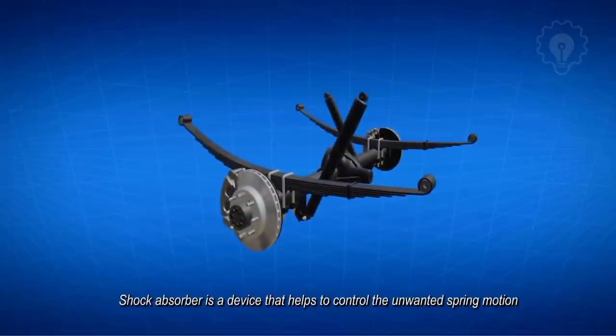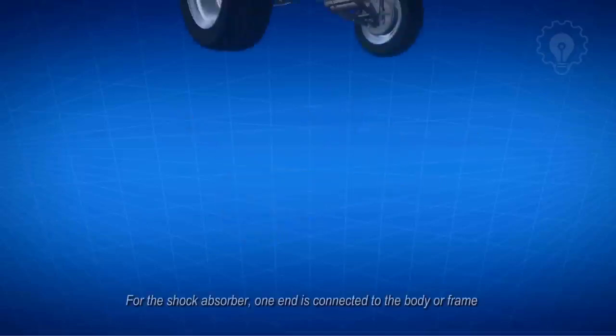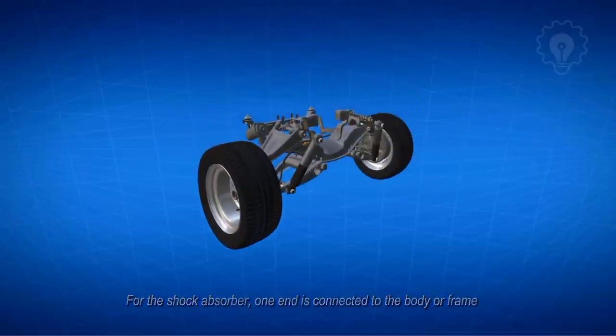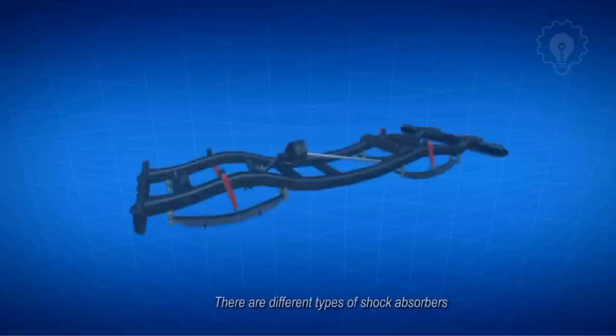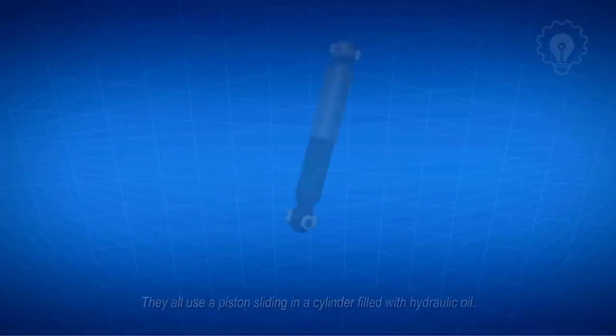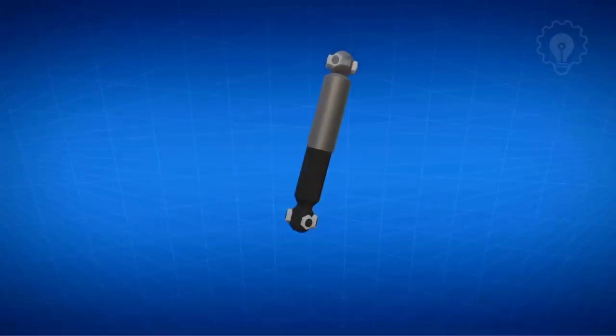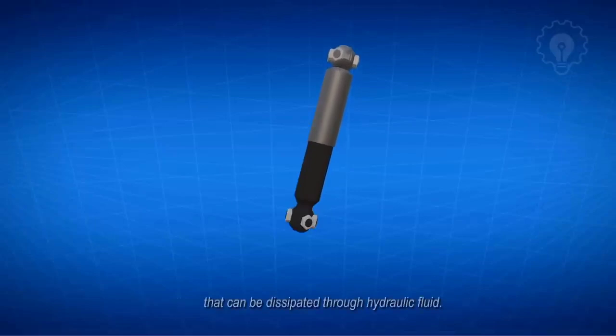Shock absorber is a device that helps to control the unwanted spring motion through a process called dampening. For the shock absorber, one end is connected to the body or frame, and the other is connected to the axle or control arm. There are different types of shock absorbers, but they all use a piston sliding in a cylinder filled with hydraulic oil. The kinetic energy of suspension movement transforms into heat energy that can be dissipated through hydraulic fluid.